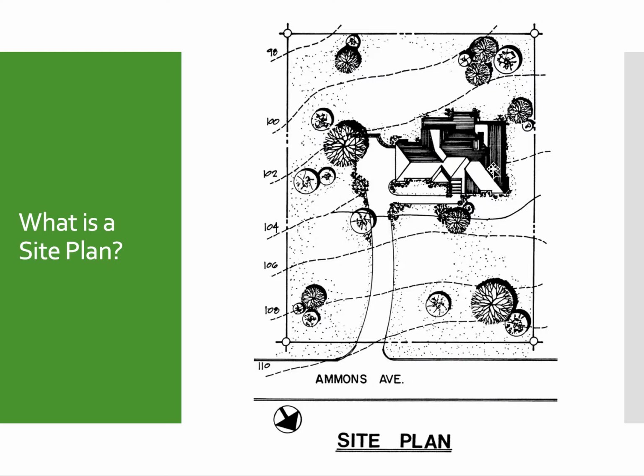But if we leave this existing contour line and put our residence here, we're going to have a drainage problem because water is draining this way. And so while the dashed lines are existing contours, and I'll show you physically in a 3D model what that is, the solid line right here should have a number associated with it over here too, just to confirm that we're making sure this stays at 10. I would have put a number over here, 104, so that 104 continues here now.